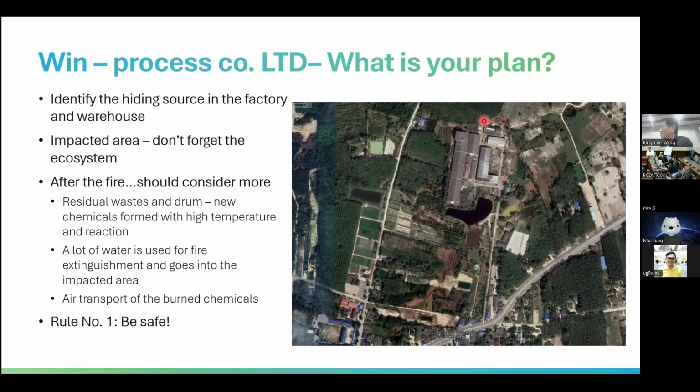So at least, if you want to know the whole distribution of contaminants, you can take samples yourself. The sampling depth would be within 10 meters, right? So we separate the sampling locations and use very preliminary information, like this area stored a lot of solvent, so you focus on VOC, TPH, or SVOC.